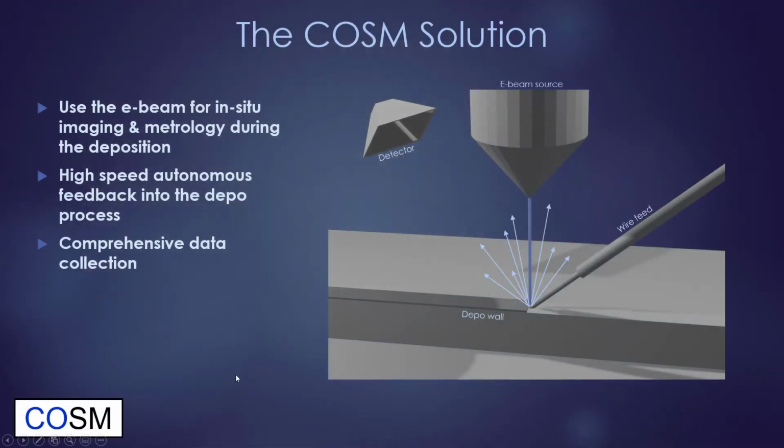In our approach to additive manufacturing, a wall of metal is created layer by layer by melting an incoming wire with a high-energy electron beam. The path of the wall is managed by smoothly moving the stage underneath the work area. Through granular control of the beam's power and scan pattern, we can not only melt the wire, but also acquire high-resolution images of the deposition as it happens and make precise measurements of how everything is proceeding at any moment